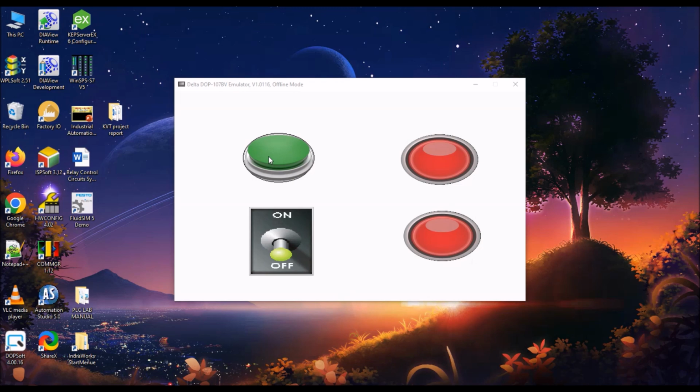Push button is like once you operate it, output is on, but when you release the switch, output is off. So as I told earlier, this kind of switch you can find in TV remote, washing machine, or lift control systems. Okay, in automation mostly we use push buttons. And toggle switch is like home lighting application, where you operate the switch, so bulb is on and you have to come back and turn it off.